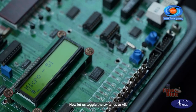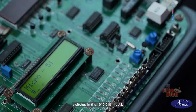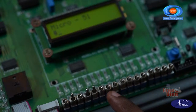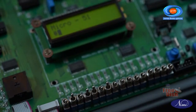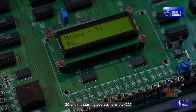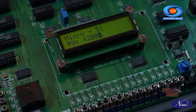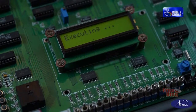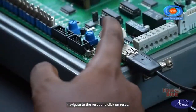Now let us toggle the switches to A5. For that, start from LSB. Toggle the switches in 10100101, that is A5. For executing the program, navigate to the keyboard and enter Go and the starting address. Here it is 4200. Then click enter. Now the screen will display executing. For performing the next action, navigate to reset and click on reset.